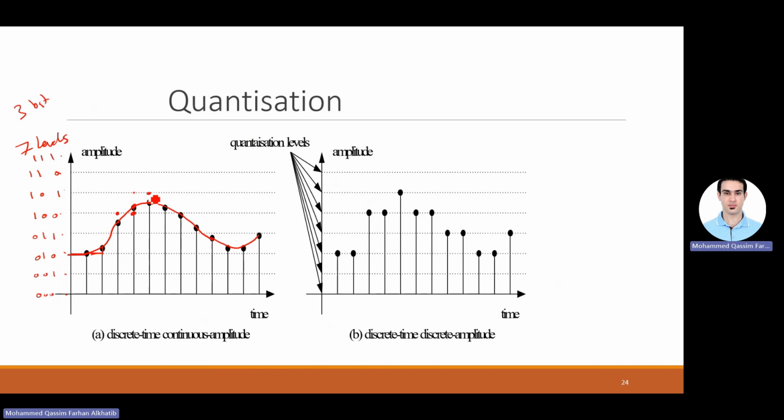This one here approximated here, this one here, here, and so on. So you have only this limited set of levels instead of an infinite set of values. Now I'm limited to these levels. So this one could be represented as 2, that is 2, that is 4, 5, 4, 4, 2, sorry, 4, that's 3, that's a 3, 2, 2, 3. And that's it. So instead of having, for example, 4.6, it got approximated to 5.